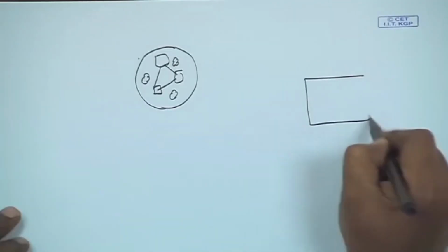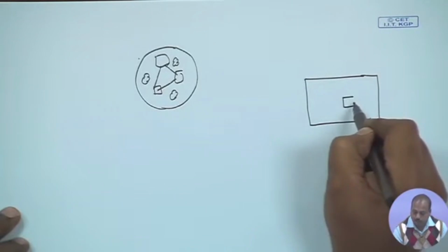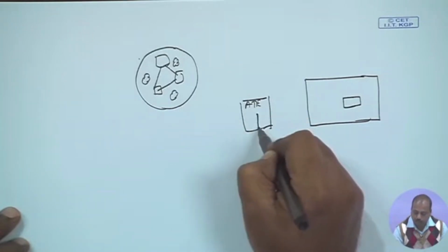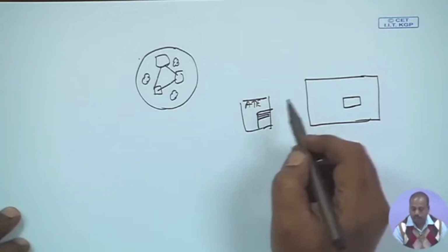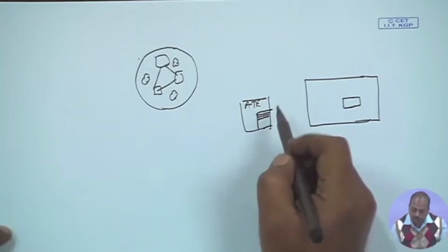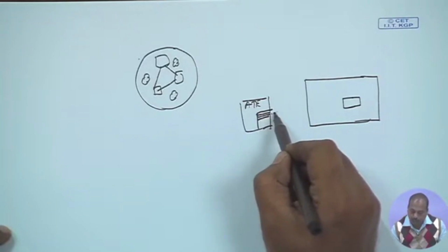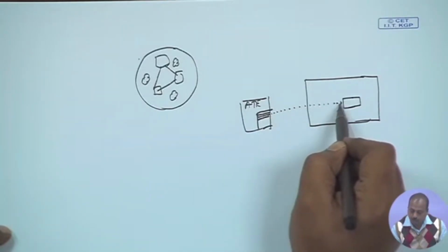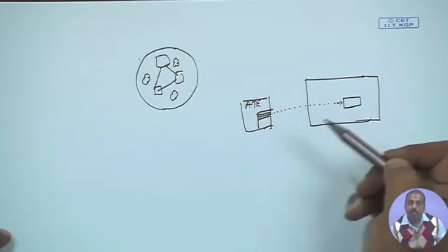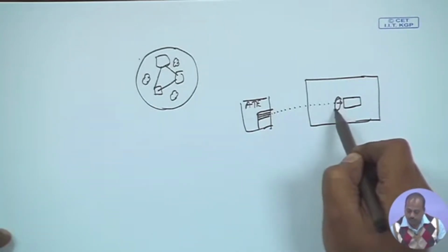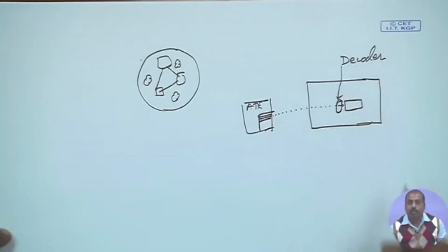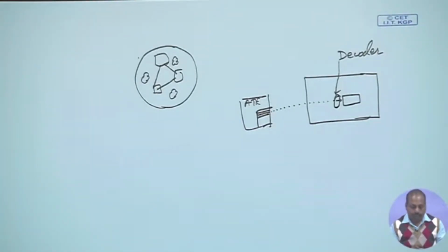It is like this. If this is the system chip that we have, and this is the core that we are going to test, in the ATE memory we have stored the test pattern for this particular core. Maybe in this region we have those patterns, but as we know, often they are not stored directly as patterns, but in some coded form. And now this coded pattern is somehow transferred to the input of the core, but this cannot be applied directly. So, I need a translation from this coded form back to the original form. So, I need some sort of circuitry acting as a decoder to get back the original pattern from the encoded bits that have been transferred.